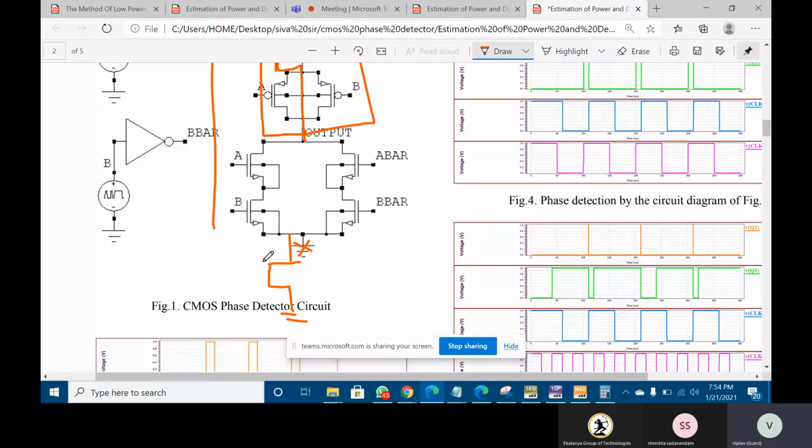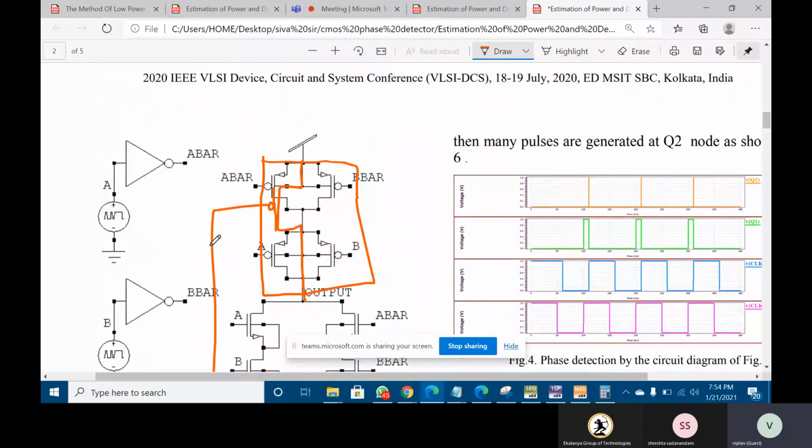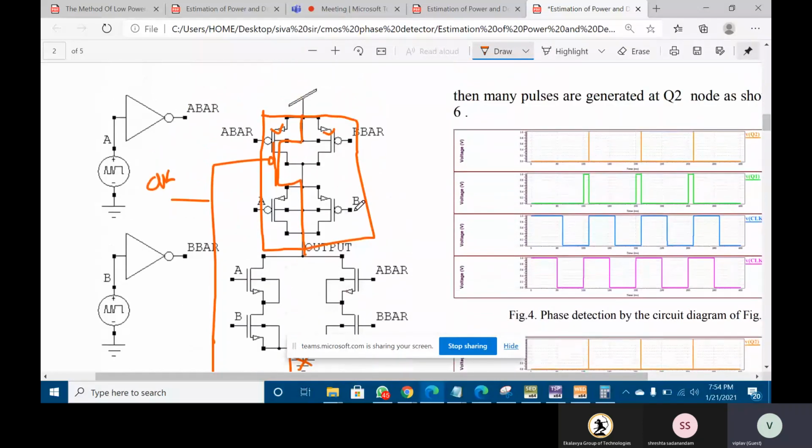So now, which is given to the control or clock signal. From that you can see now, before it was one transistor, two transistor, four total, 1 2 3 4, four transistors. So 4 transistors for the pull-up and 4 transistors for the pull-down network.